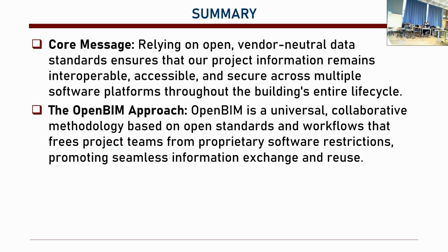Basically, we want to rely on an open and vendor-neutral data standard. Okay, so we don't want to rely on Autodesk, Graphisoft, or Bentley, these companies' software versions and software file formats. We want to have an open, neutral data standard so that our project information remains interoperable, so it can be used by many different software environments directly. Accessible, so we can exchange that model with many people, they can use it. And secure across multiple platforms through the entire lifecycle. So that IFC file, we can open it, let's say, 20 years later, 50 years later, because there is an international body, buildingSMART, maintaining that standard so that it can be translated.